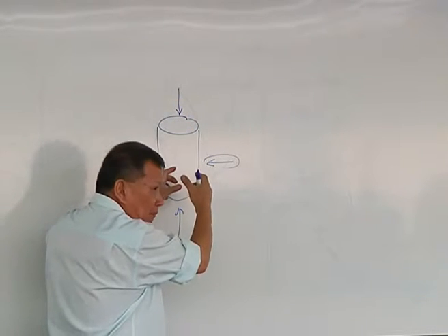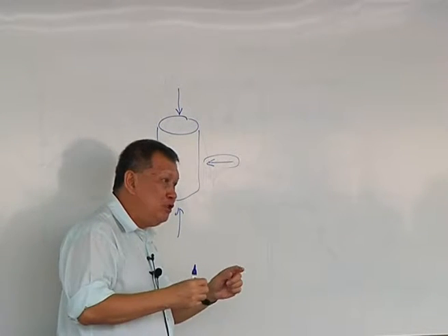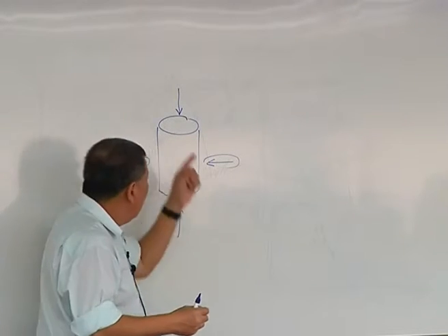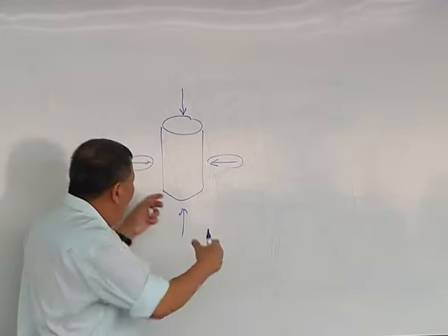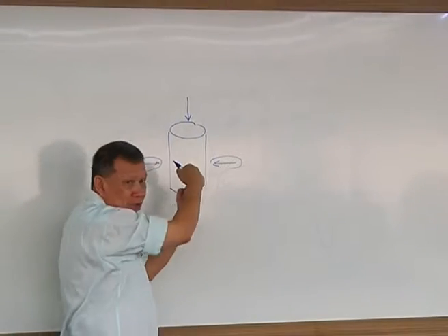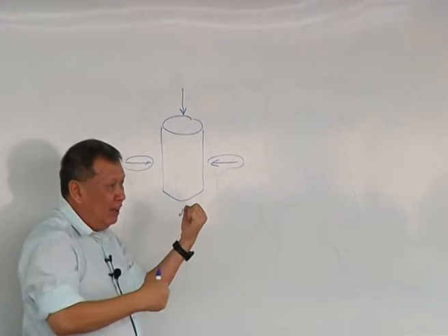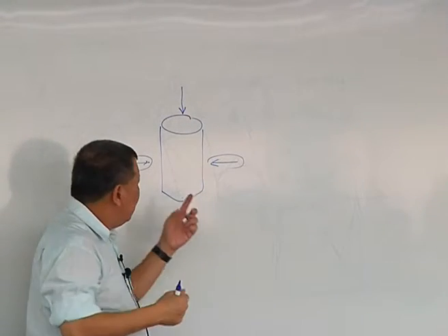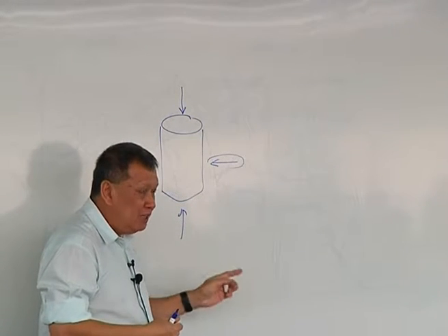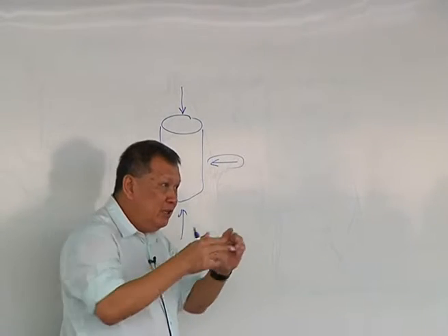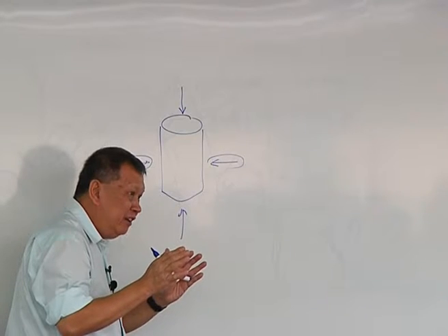There may be a small amount of elasticity, but in fact, what you are doing is inducing shear stress, deviator stress, because sigma 1 minus sigma 3 starts to increase. And as a result, if you reduce it too much, the whole thing will just squash underneath. That's why I say that it depends on how your yield condition goes. In this particular case, in soil, or I suppose in the plastic material you're talking about, shear stress features very strongly in the yield condition.